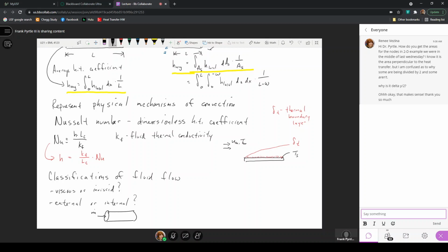There's a velocity associated with the fluid, such as if I have a mass flow rate, and the mass flow rate is the density times the cross-sectional area of the pipe times the velocity. Well, if the pipe diameter is constant, then the cross-sectional area is constant. If the density is constant, then it says that the velocity would be constant along the length of the tube or the ductwork here.